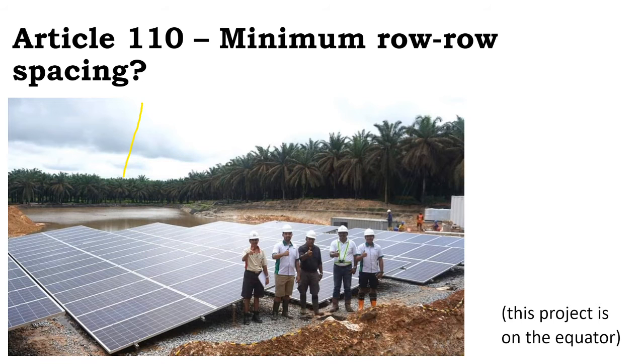but if you wanted to be fancy, like if you were designing not just one row of modules with a little short shadow, but something with a higher tilt or something with a longer space, that electrical spacing, if there's 4 feet behind you, that would allow you to actually get down and crawl underneath this array and get back out without bunching up against the module. If there's no spacing in between these things, you're going to have to Spider-Man across the array, and that creates a tripping hazard, a falling hazard. It's just not as comfortable for a worker.